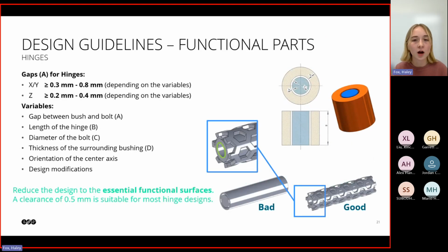Getting into hinges. If there are aspects of your design that might benefit from this, I really like talking about hinges because there's a lot of interesting design changes you can make in additive. There are some different gaps that you want to consider if that hinge area is being printed in X and Y versus Z. But an interesting picture here is actually how heat really makes a big difference when we're talking about hinges.